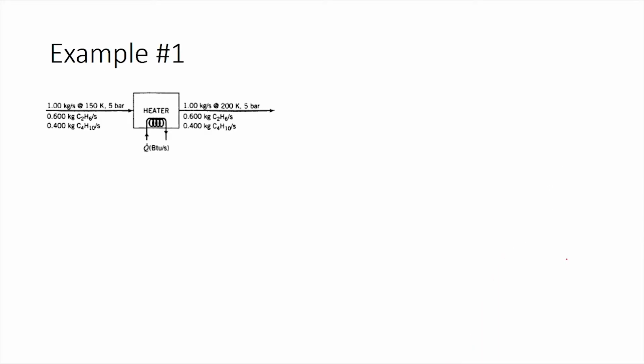So, this is an open system, which means the energy balance for this system would be delta H dot plus delta E_k dot plus delta E_p dot equals Q dot minus W_s dot. For this system we have been asked to ignore kinetic and potential energies. So, these two will go to 0. There are actually no moving parts in the system like a piston or things like that. So, therefore, the shaft work would also be equal to 0.